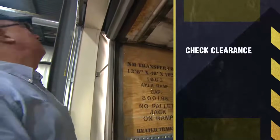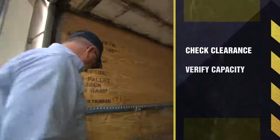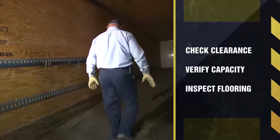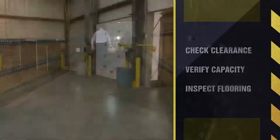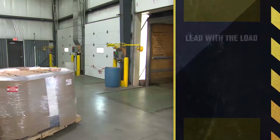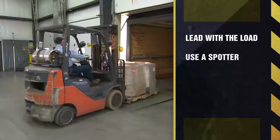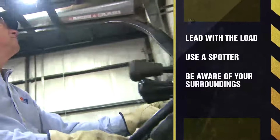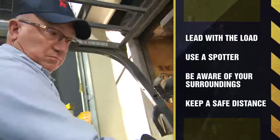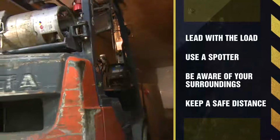Verify the forklift mast will clear the ceiling, and make sure you won't exceed the trailer's capacity rating. Also, inspect the flooring for obstructions, loose objects, holes, or weak points. When you enter a tight area, enter with the load end leading. Use a trained spotter to guide you, especially when the load restricts your visibility. Always be aware of your surroundings and maintain a safe operating distance from the walls and product inside the tight space you are operating in.